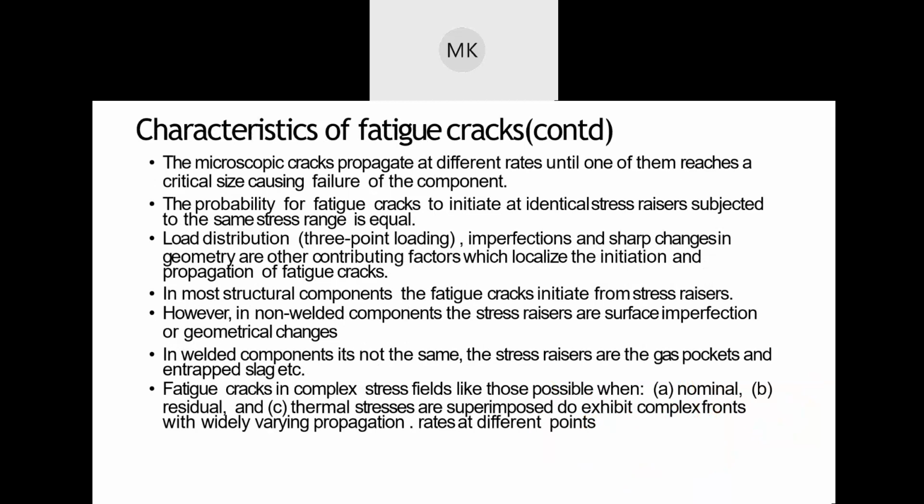So the crack initiation part can happen pretty soon in the material. Within the first 1,000 material cycles, you can have all the cracks initiated in the material. But for you to have a major crack growing in the material, it might take even millions of cycles. Anything above 10,000 to about a million cycles for the major crack to be formed, and then you have slow crack growth, and then it leads to failure. So all these things can take a long period of time, depending on how the grain boundaries are, what are the sizes of the grain boundaries, and the number of grains that you have.